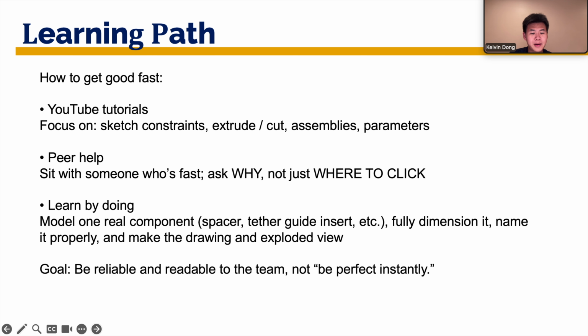You can also learn by doing. Pick one real sub-component, like a wheel spacer or tether line guide insert, and model it clean, fully dimensioned, fully named, with a drawing. Then hand that off to manufacturing as a test. Your goal is not to be a CAD god today. Your goal is to be reliable and readable for the team.